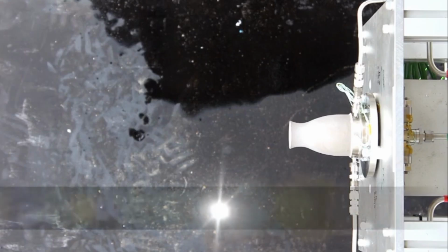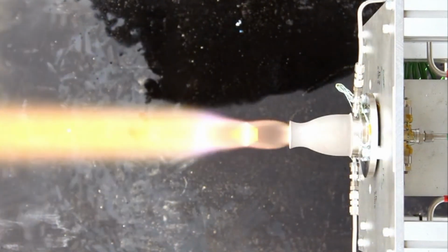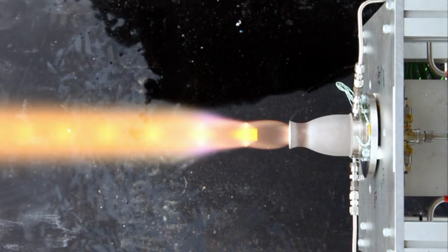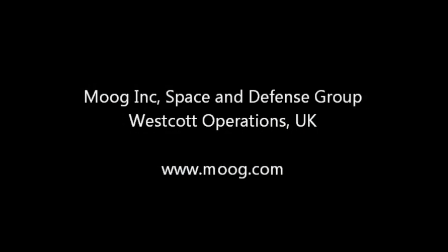Here's an example of the fuel film cooled Leros engine. In fact, the larger Leros 4 space engine developed by Nammo, which I worked on, using hydrazine and nitrogen tetroxide storable propellants. And another example of a large fuel film cooled engine from Sheffield University.